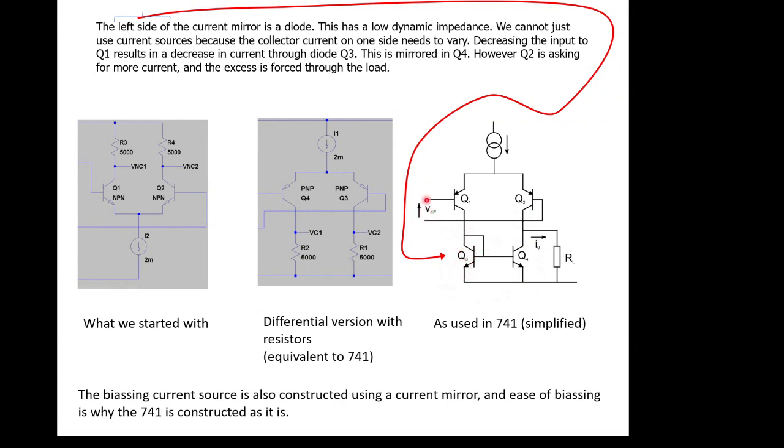And whatever happens here, you change the voltage here, it goes up. We get more current going down here, more current going through the current mirror here. This is connected to this transistor. It's got exactly the same VBEs because of the way they've been connected. So this one wants to have exactly the same current as the one going through here. But remember, the voltage on this one has gone down with respect to this. And so this transistor is saying, in this case, I'd like less current, please. This current source is saying, well, I'm going to have the same current running through here. So the only thing that can happen is more current can actually come from the load down through this resistor to make up the difference.